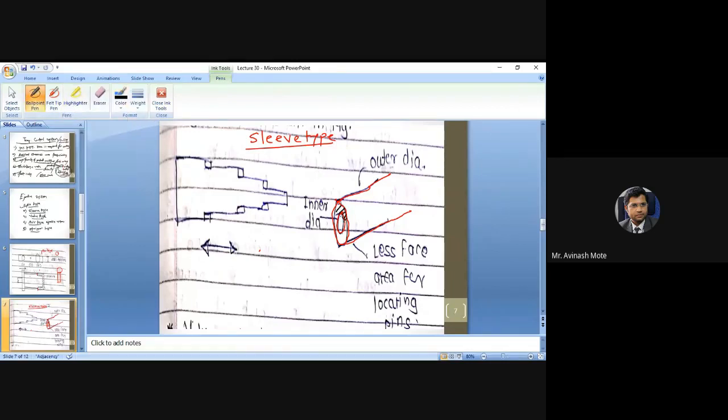On this surface, on this solid surface. Check out the surface area. This is very less. So I cannot keep one pin at this side and one pin at this side. Getting it? So this is a totally different kind of product. In this kind of product, where products are hollow, the effective surface area is very less, so we cannot go for the pin type ejection system.